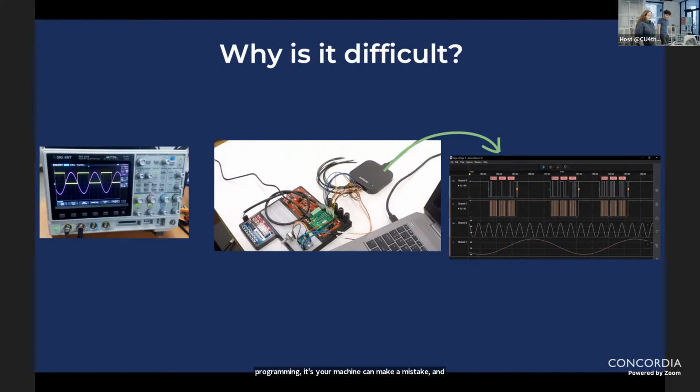One of the simplest things that we have debugged before in our space lab is using a voltmeter. We realized that some of the pins had been connected wrong, so the power wasn't going where it was supposed to. And after an hour of trying to debug the software, you figure out it's actually a very simple mistake. Yeah, some pins weren't connected in the proper slots, and we thought that they were connected the whole time. So the emphasis on having an eye out for these things is quite critical.